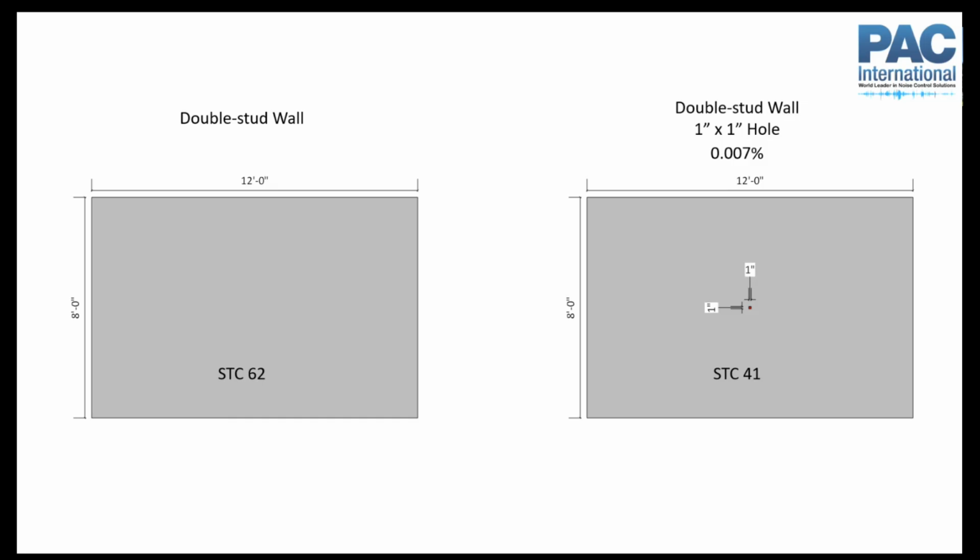I worked as an acoustical consultant for many years, and there were times I would get brought in because some office space had 2 conference rooms next to each other, and they were hearing conversations back and forth between them, or they just didn't get the level of sound isolation that they wanted. I'd go in and do some tests and investigation, and it might be that they just hadn't sealed the drywall to the floor at the bottom.